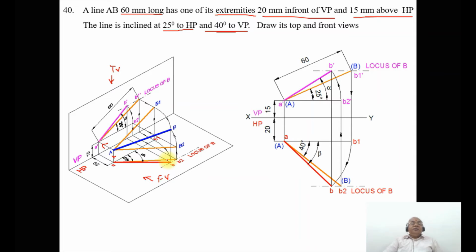So you can see, when the line is parallel to HP, the image is going to fall on the vertical plane. Therefore, you have to look in the vertical plane. Now, in the vertical plane, A dash B2 dash is parallel to HP. So therefore, you are going to get the true length in HP. How do I identify that here?